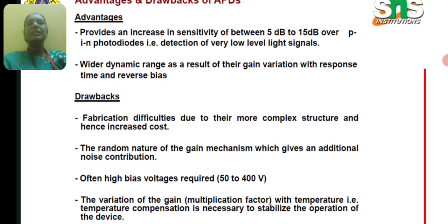So, some of the advantages and drawbacks of APD. APD provides increased sensitivity and wider dynamic range, though the gain varies with response time and reverse bias.